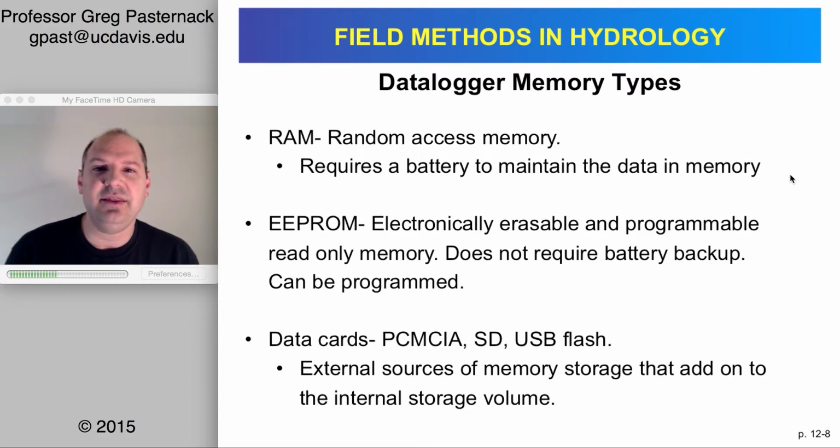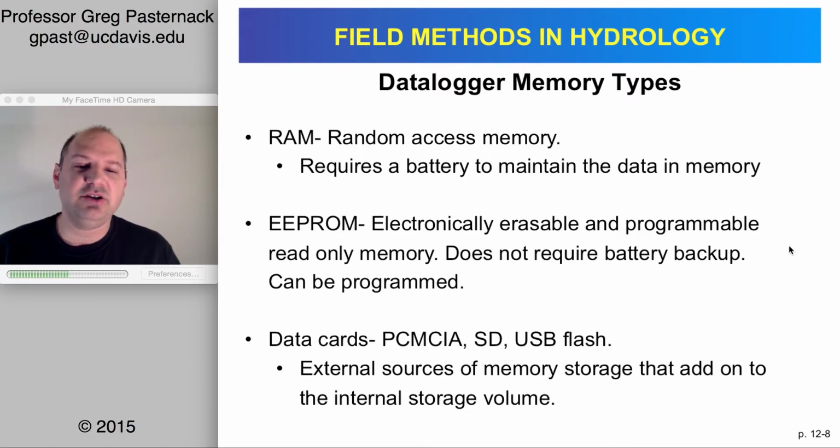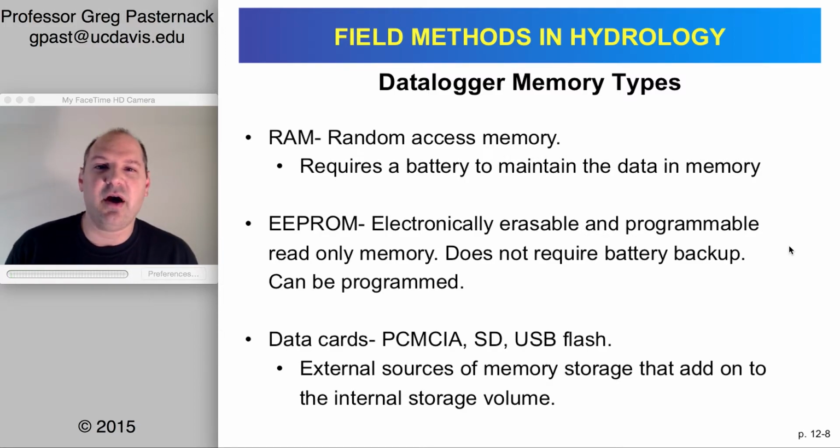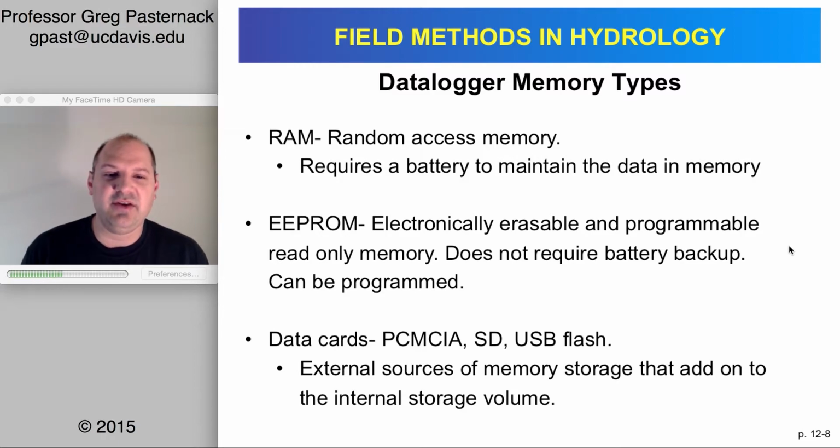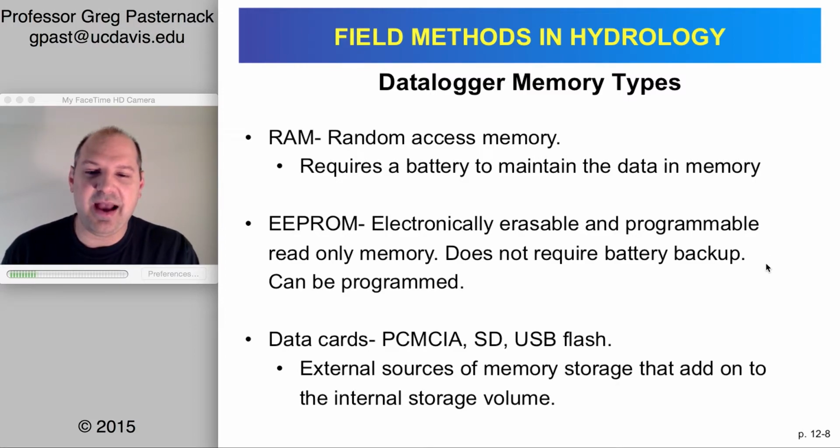So you have a battery, and there can be the overall large battery that runs the whole system, and then there can be a small little LR44, these little jewelry sorts of batteries, that can be used to just maintain the data against all other failure. In addition, a data logger is going to have some fundamental programming built into it, what we call ROM of some kind, or EEPROM, electronically erasable and programmable read-only memory. So this is read-only memory. It's like it's locked onto the system, but usually these days there's some kind of way to upgrade that firmware and give it new information. This does not require a battery backup.